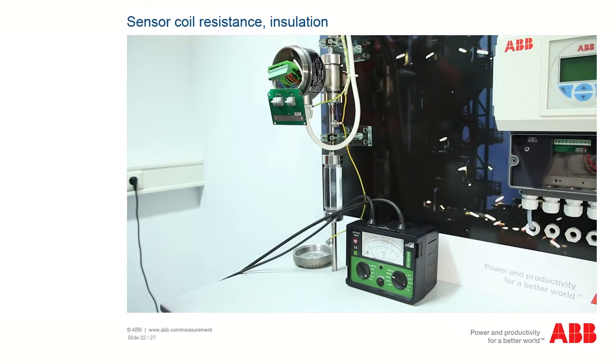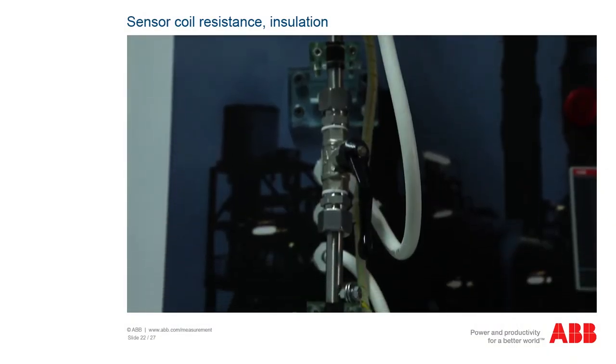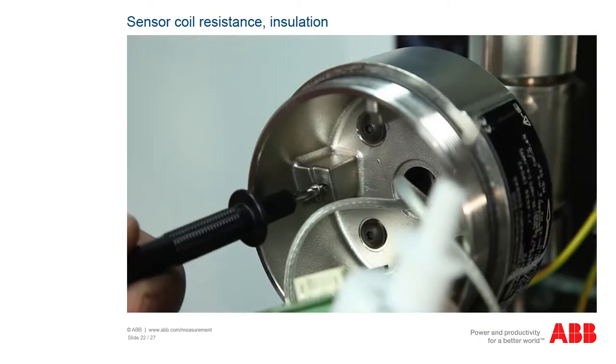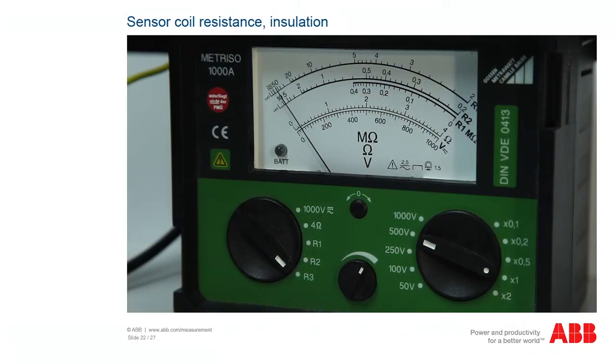If the coil resistance value is correct, measure the coil insulation. You can do this with the coil installed and with the meter tube full. To do this, connect the earth of the insulation measuring device to the sensor housing. Measure the insulation of the coil with a voltage of 500 volts. Caution: high voltage. Proceed with extreme caution in the following steps.